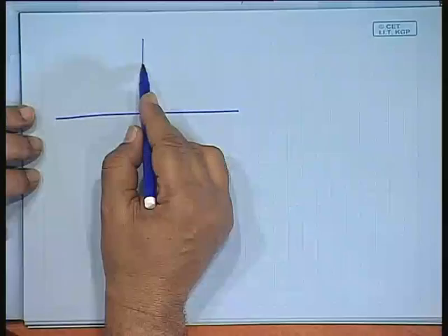Third order Butterworth filter will have a unique position of the roots, whereas third order Chebyshev filter will have roots depending on the value of epsilon. So, every time you have to compute the roots separately. Now, that is quite laborious, but anyway there are shortcuts. Standard design books have given methods of computing it. One of the simplest methods is to find out the roots of the corresponding Butterworth filter.